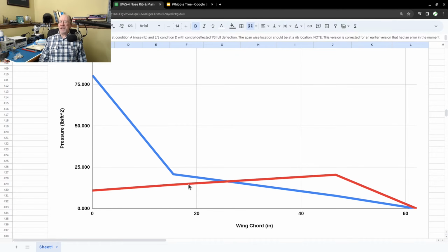So here's that load chart again. Now the spar is back here. This is inches down here, and the spar is about 19 inches, so that's right around in here. That's awfully close to being triangular shaped with a little bit of extra offset, lifting it up a little bit higher. Now, if it was strictly triangular shaped, let's say it came down to 0 here at 19 inches and then came up, then I know that the load centroid would be 1/3 back. So a little over 6 inches, about 6 1/3 inches, about 6.5 inches back from the leading edge if this was strictly triangular shape and didn't have this extra little bit down here.